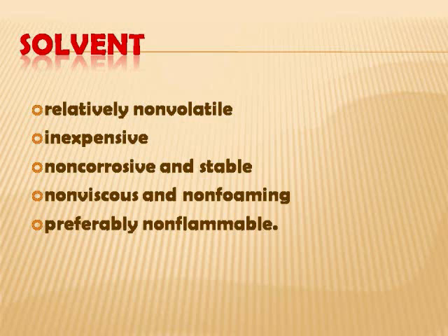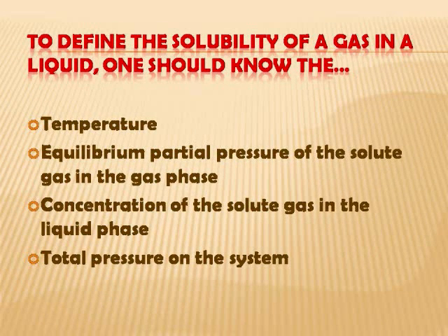Solubility values actually play an essential role in the design because they determine the liquid rate necessary for complete or economic solute recovery. And for us to define completely the solubility of a gas in a liquid, it generally is necessary to state the temperature, the equilibrium partial pressure of the solute gas in the gas phase, and the concentration of the solute gas in the liquid phase.